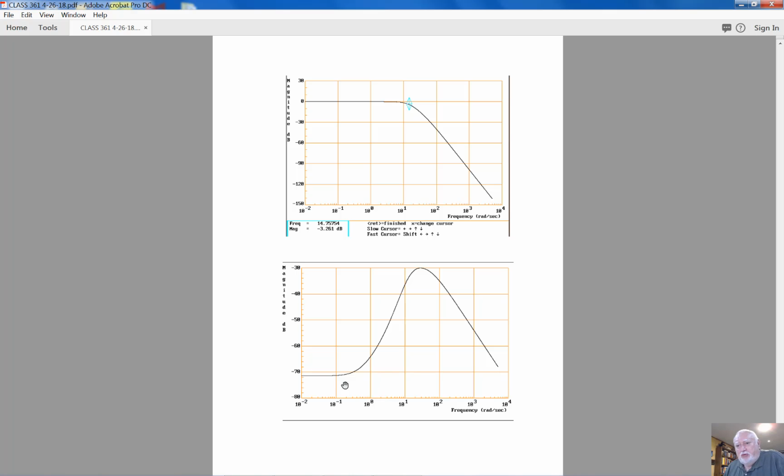When it comes to the disturbance rejection, I got the frequency response for our designed system for the disturbance input. And this is what I have. What you can conclude by looking at this frequency response is this. The entire magnitude of the frequency response of our system is below minus 30 decibels.